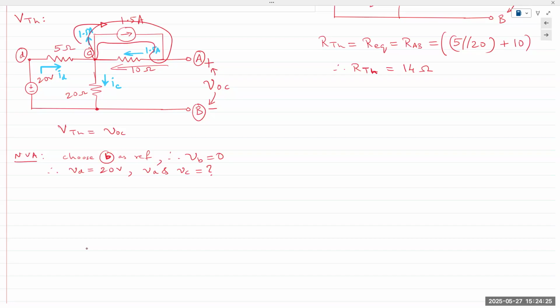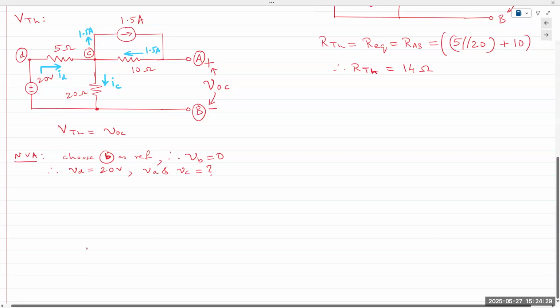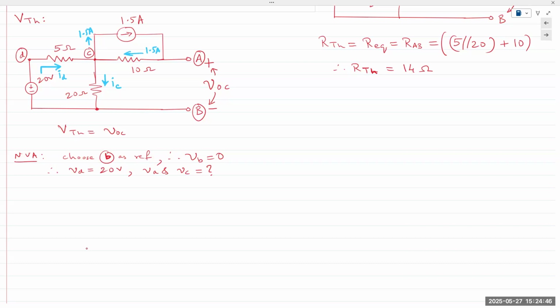So what do you think is going on with the current source and the 10 ohm resistor? And the answer is there in the arrows, of course. It is just looping around itself. It's not doing anything, it's just looping around itself, which is not quite obvious with the way the circuit is drawn, but because it's an open circuit over there and there's a short over here, learning moment, if you have something like this, that's a closed loop and it's a current source, current's going to keep flowing through there. Nothing else is going to happen.